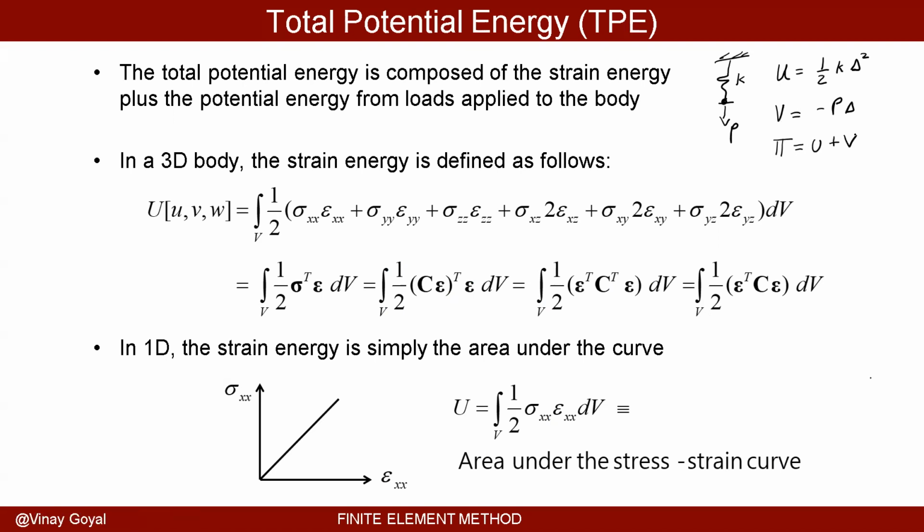But what happens in a 3D body of material where stresses and strains are acting on the body? The idea there is that you do have a strain energy, and that strain energy is going to be equal to the integral over the whole volume of the stress in each direction multiplied by the corresponding strain in each direction.